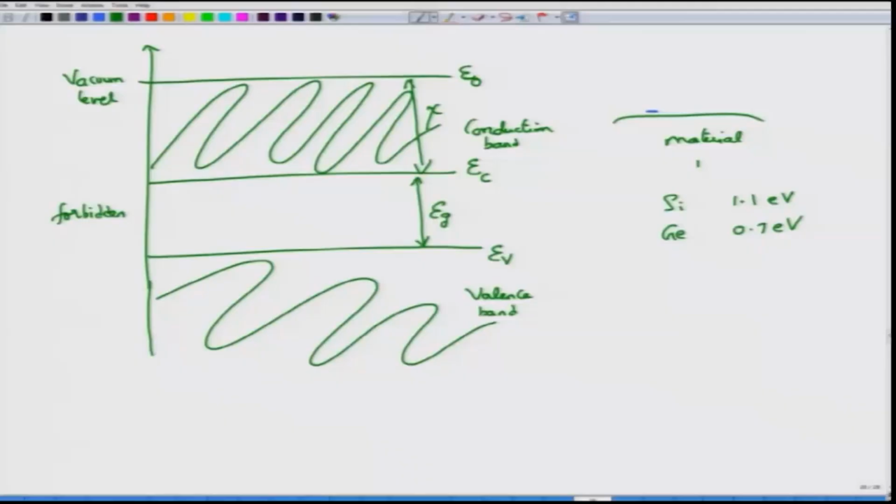So, at ordinary room temperatures, there is thermal energy present which is sufficient for some of the electrons to actually jump over from the valence band and be present in the conduction band. Semiconductors are found in the group 4 elements mainly, and examples of those group 4 elements are silicon and germanium. These have a particular structure, called a diamond structure, in which each silicon atom shares electrons with its neighboring atoms.